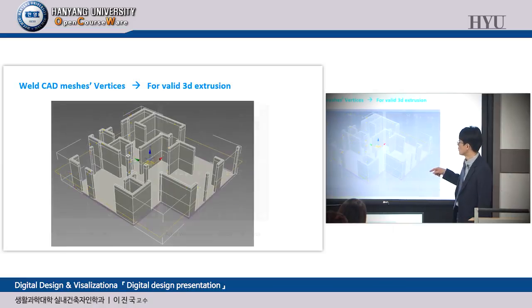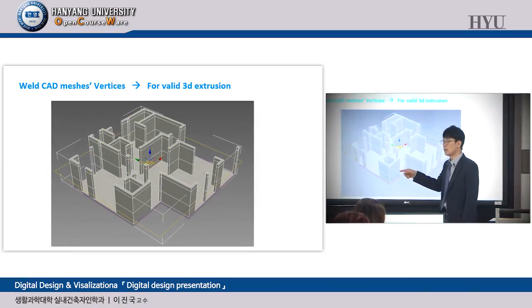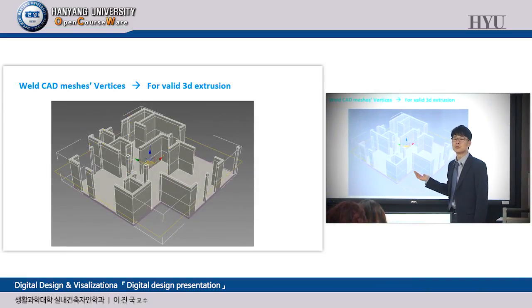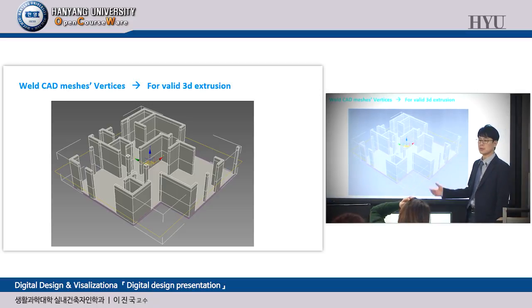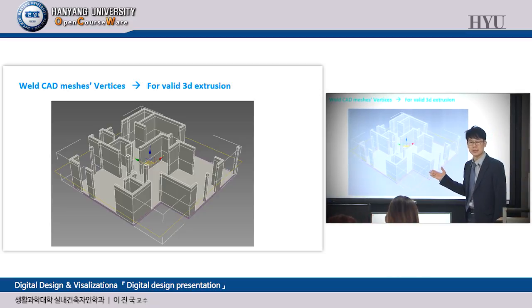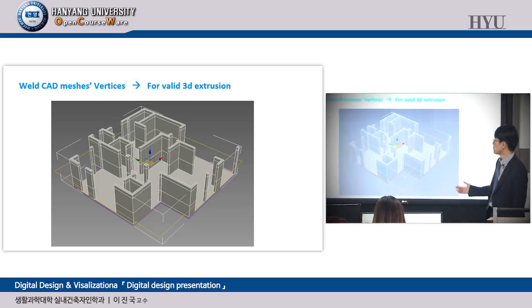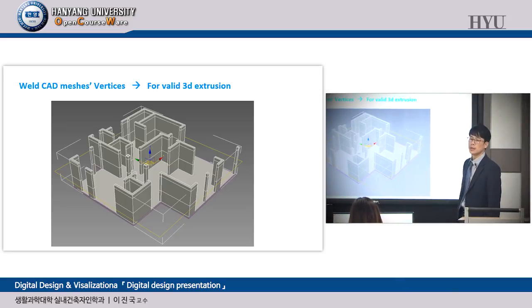So we can make this kind of solid-looking 3D geometry without any hollow inside wall, okay? That's exactly what we have used in lab exercise hours, okay? So this is the difference between solid and surface-based 3D definition.